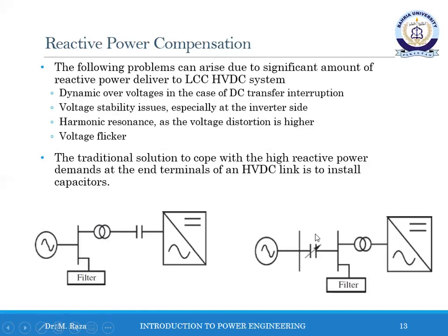This solution is called a controlled series capacitor converter and uses a thyristor controlled series capacitor placed between the power system and the AC transformer. These advanced configurations have the advantage that they can operate in a weaker AC grid and that they can also withstand voltage drops much better. Furthermore, the reactive power requirements are significantly lower.